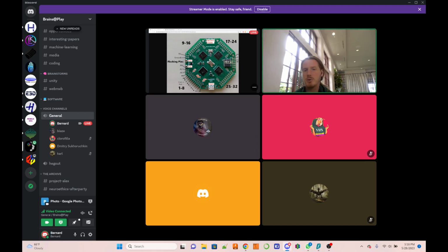If you wanted to, and I think this is possible with the Cyton, I'm not sure, you could make every individual channel have a completely different montage, with its negative terminal on a different location. It also means you could use every channel for a completely different function, like EMG or EKG, because every channel has a full pinout.